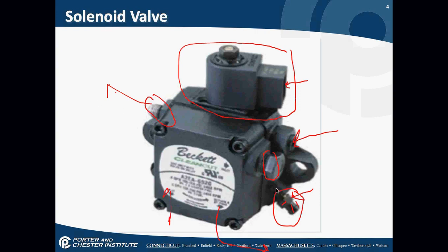So this is where I have to jump out the primary control while the pump is running with my 3/8 inch open-ended wrench that I've used to open this. Once I get a clear flow of oil, I can close this with that same 3/8 inch wrench that I just had in my hand already. I could do my pressure adjustments, I could check my vacuum. This is all here on the oil unit, on the fuel unit. This is my solenoid that's built into the oil pumps, the newer pumps. That's the whole setup of an oil pump.